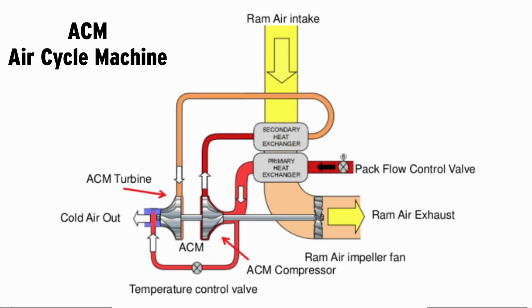You took what was originally 200-plus degree temperature air, and you've brought it down below freezing, not by using a refrigerant, just by using some heat exchangers and making it do a ton of work. That's the power of thermodynamics, which is super cool. And it comes out of there so cold that it actually has to run through a dryer to spin out any moisture, because that's going to be bad. That's going to freeze in the airstream now. So you've got to get the moisture out of there.